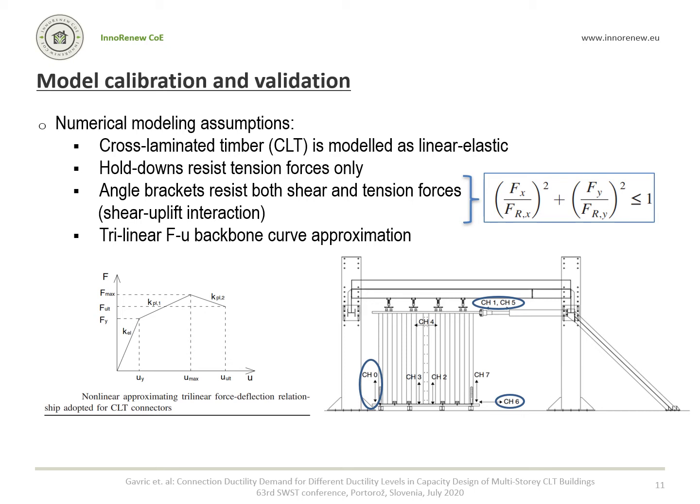We made the following assumptions in numerical modeling. CLT was modeled as linear elastic material. Hold downs were assumed to resist tension or uplift forces only, while angle brackets were assumed to resist both shear and tension forces, with an additionally applied shear-uplift interaction domain.